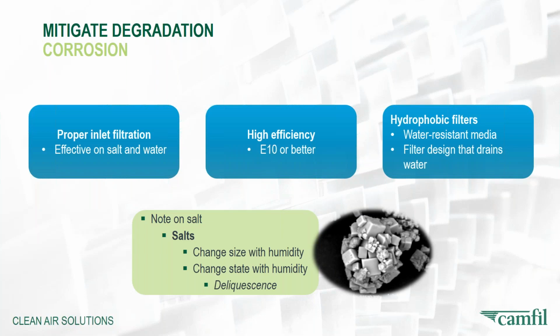From a filter standpoint, up to a given level, that's a good thing, because generally speaking, bigger particles are easier to stop and retain than smaller particles. However, there's a transition point around 70 or 80% humidity where that same salt particle will change its state. It will go from a solid particle to a droplet or a liquid, and that term is called deliquescence.